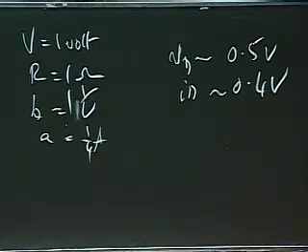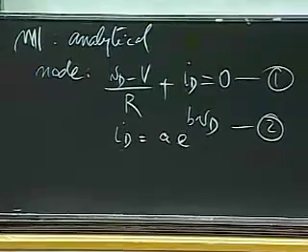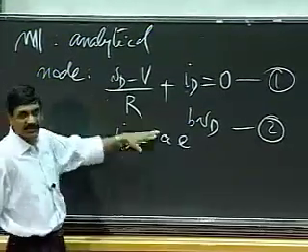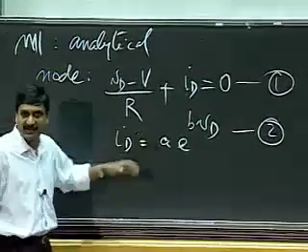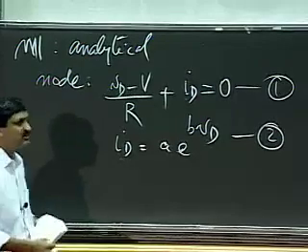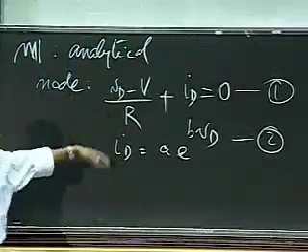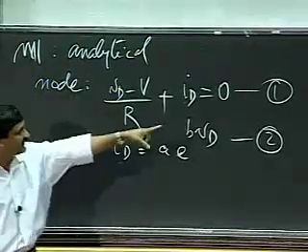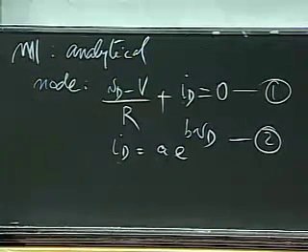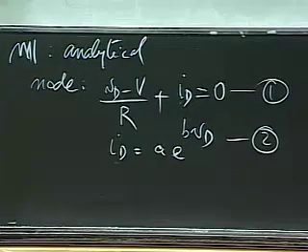In 6002, we don't dwell on working too hard to solve equations of this sort. If you cannot substitute this in here and solve it directly, we don't ask you to learn numerical method techniques to solve it. But remember that you can use trial and error, or back substitution and other techniques that you'll learn in future numerical methods classes. For here, we can stick with trial and error. For these values, VD and ID are 0.5 and approximately 0.4. We're done. It's really that simple.